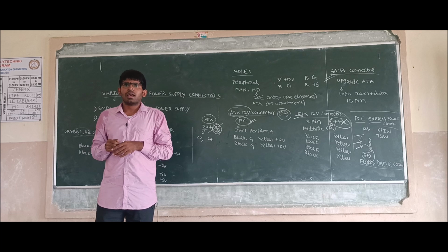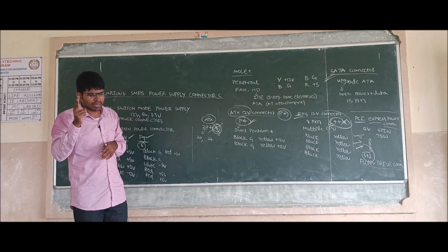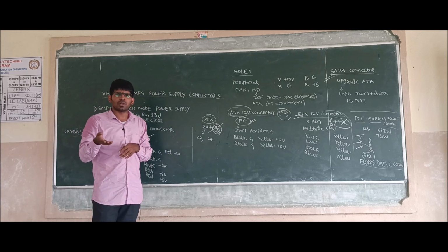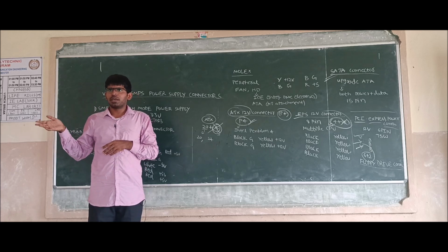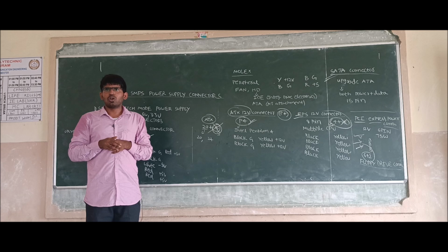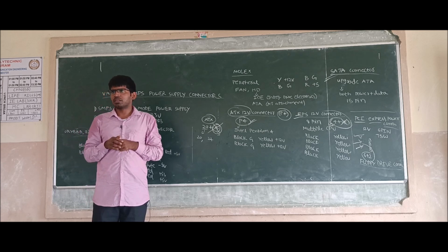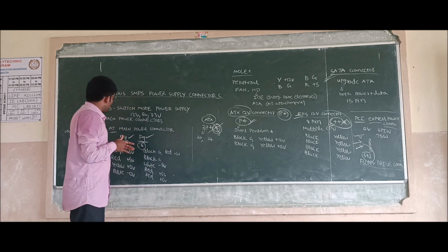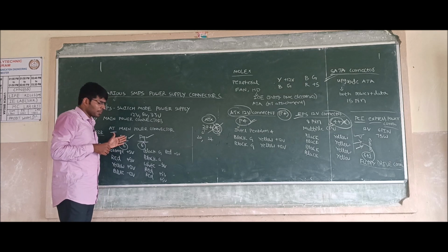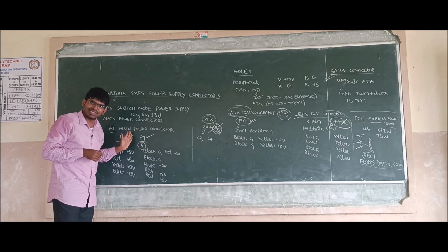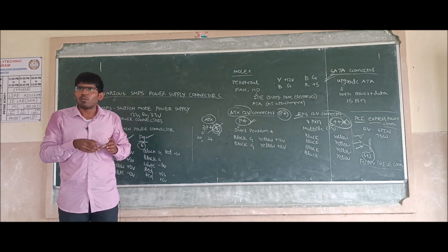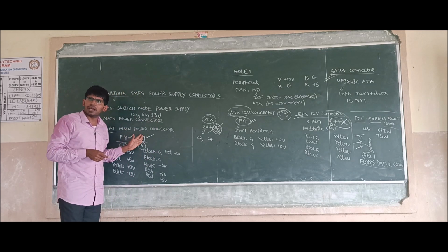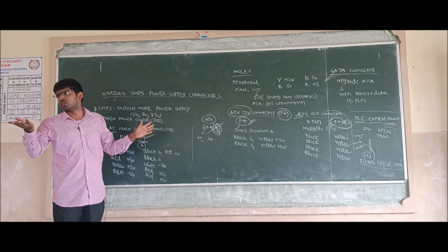Very good. Apart from these, we have green and grey also. Those you do not require at present. The green one we require to communicate from the SMPS to the motherboard at the time of power on, and one is grey. Now we discussed initially P8 and P9 connectors. These are AT connectors or ATX connectors? AT connectors. How many pins do P8 and P9 have? 6 pins. Very good, 6 pins.